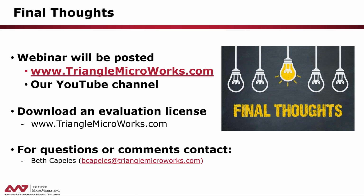Okay, next question. Is there a security recommendation for GOOSE traffic when it is leaving the substation? Yes, there is. Our GOOSE includes encryption and authentication. We're currently working on an implementation of a Key Distribution Center GDOI client that works with a GDOI server to manage all those keys.